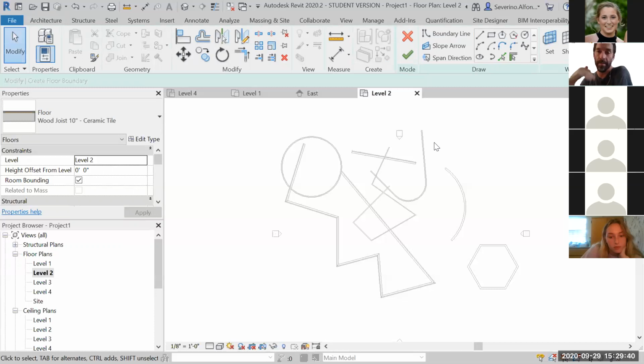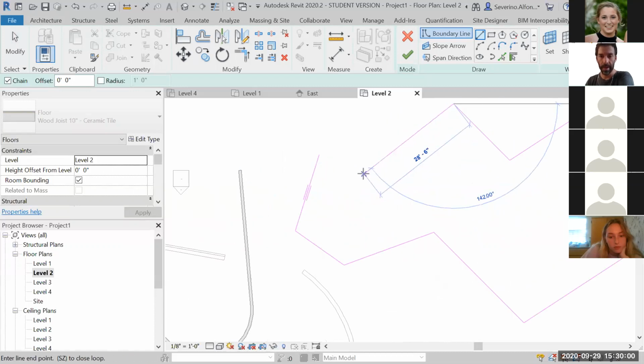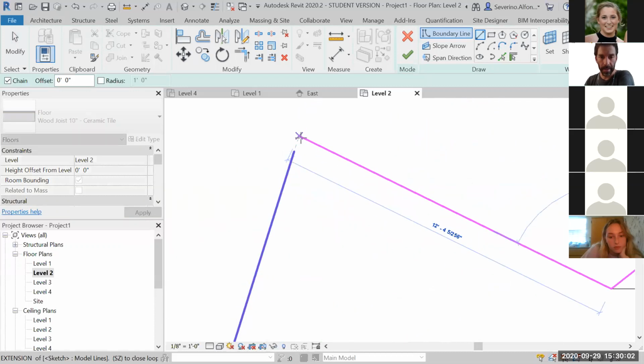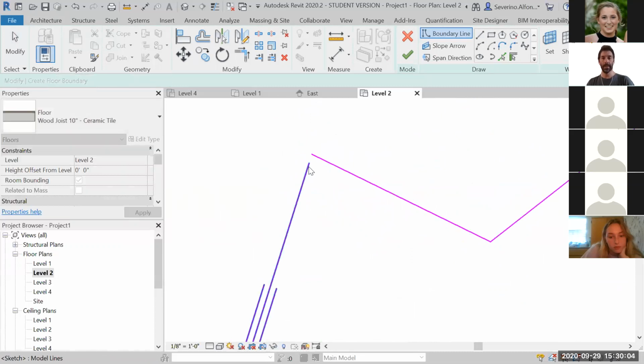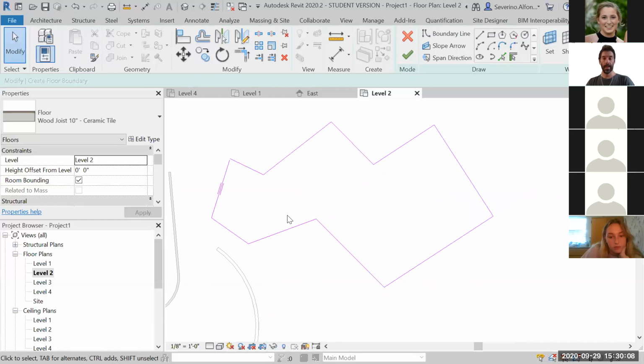The way it works again, for floors, ceilings, and roofs, is that you draw a closed polyline. What I mean by closed is very important, that is closed. So I'm going to do something intentionally wrong. This polyline will be in magenta. Imagine I want a very funky wall, a floor, sorry. I go there and I leave that unclosed. This is not closed, it's open. And I say, this is the shape of my floor. I'm done.